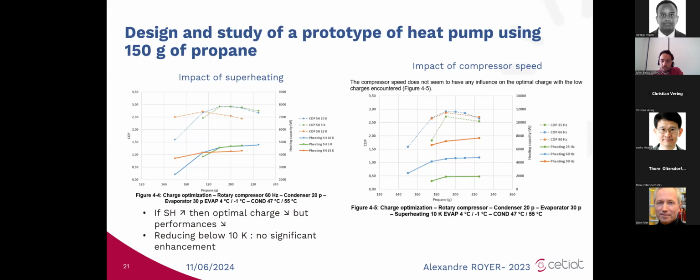As we were working here with some really low charges, it didn't really seem to have a big influence, but maybe also because those compressors weren't completely designed to work with this amount of refrigerant. And also, if I remember well from the test, there were lots of issues with oil, and too much oil in the whole circuit.